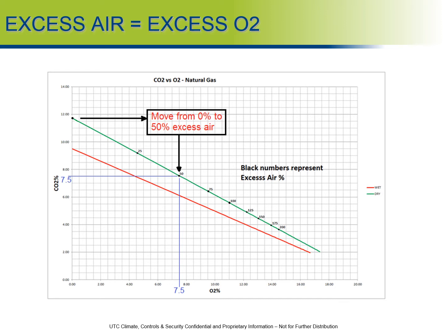Adding that 5 cubic feet of excess air is 50% of our original 10 cubic foot value, so that's now referenced as a percentage of the initial 10 cubic feet. So as you can see here, this is essentially an almost perfect combustion on a gas burning appliance.